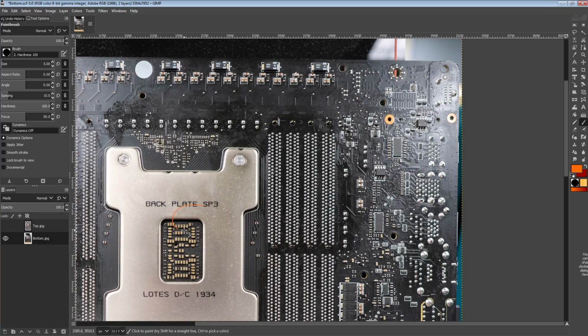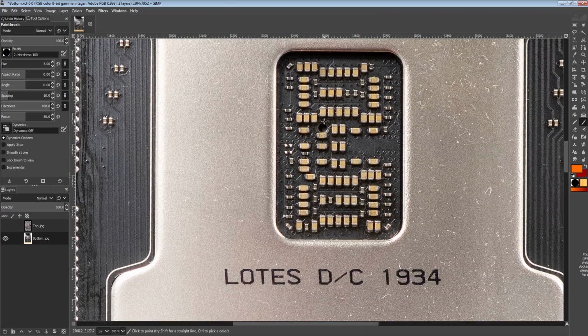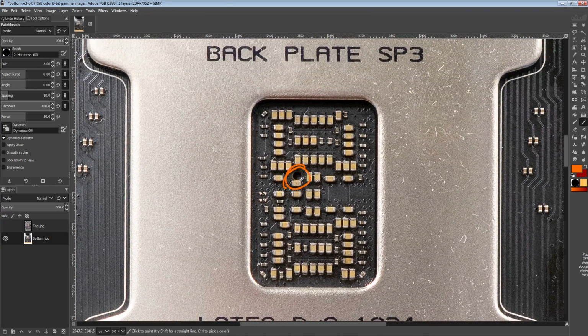And then if we go on to the back of the board, we get a very extreme overclocking focused feature. We get this hole in the CPU socket, which is for putting thermocouples through, though technically you could also solder voltage probes through that, though good luck squeezing them through that hole. But yeah, you can put a thermocouple through that and basically monitor the CPU temperature without having to rely on the built-in temperature sensors of the CPU, because those don't tend to work very reliably once you're very far below zero.